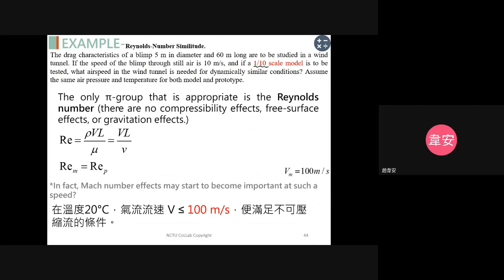So for this problem, the only pi group that is appropriate is the Reynolds number. There are no compressibility effects, free surface effect, or gravity effects, because our problem only involves the viscous effect, related to the drag force.